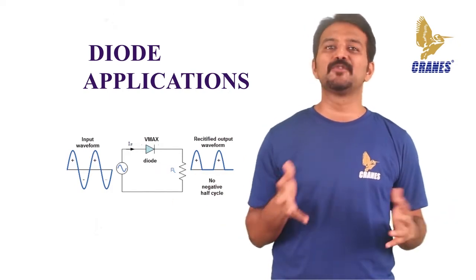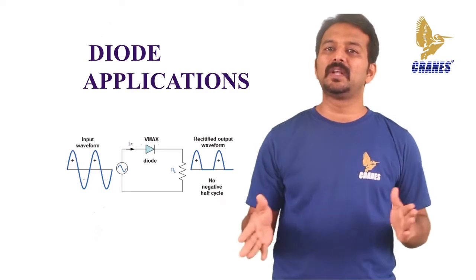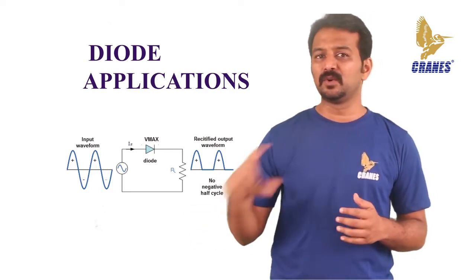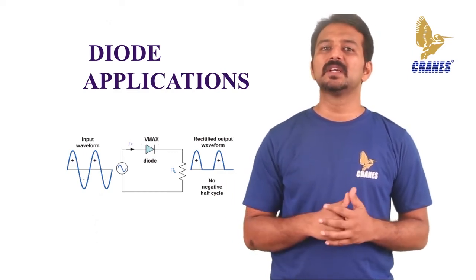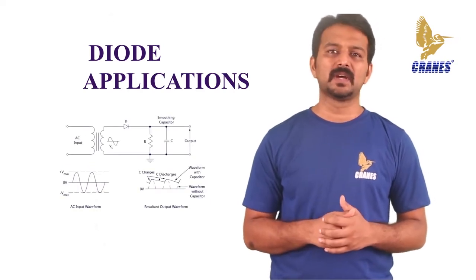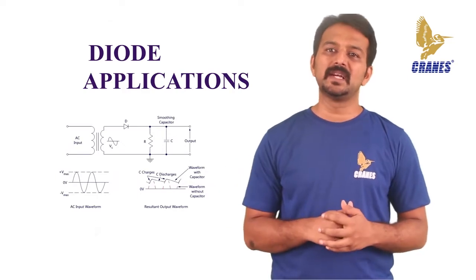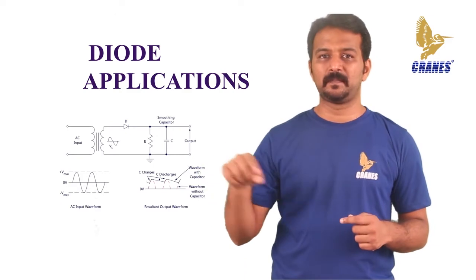Hence, no current flows through the load. The circuit becomes an open circuit. No voltage appears across the load. Both the voltage and the current at the load side are of the same polarity, which means the output voltage is pulsating DC. Very often, this rectification circuit has a capacitor that is connected across the load to produce a steady and continuous DC current without any ripples.